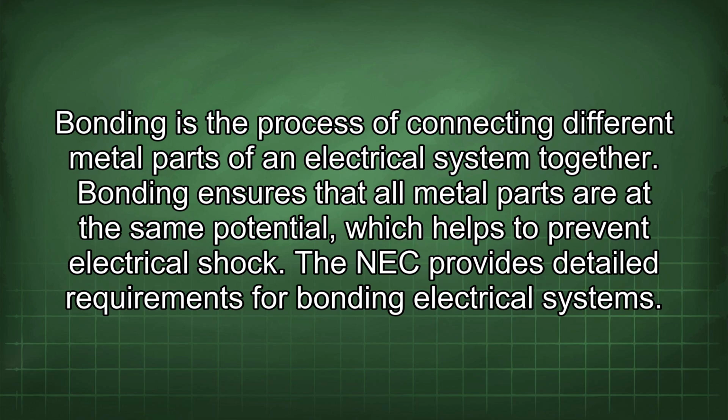Bonding is the process of connecting different metal parts of an electrical system together. Bonding ensures that all metal parts are at the same potential, which helps to prevent electrical shock. The NEC provides detailed requirements for bonding electrical systems.